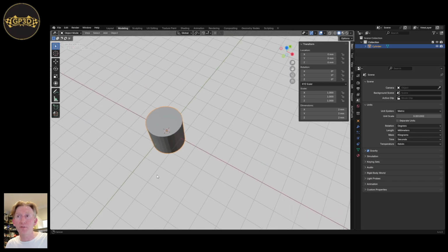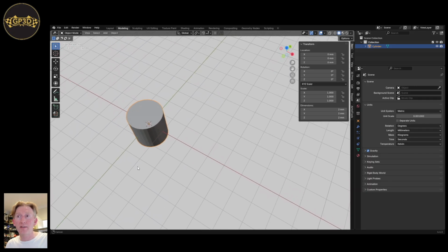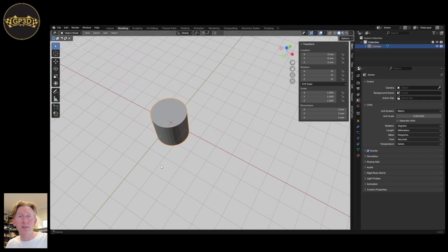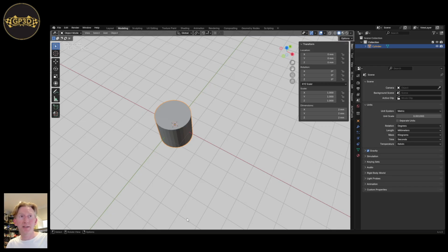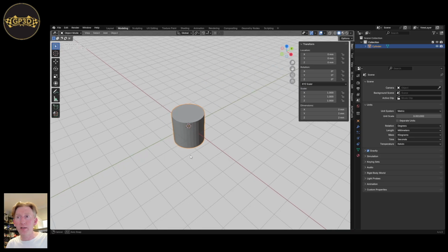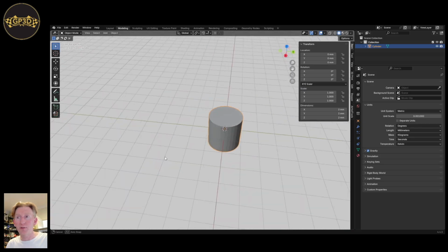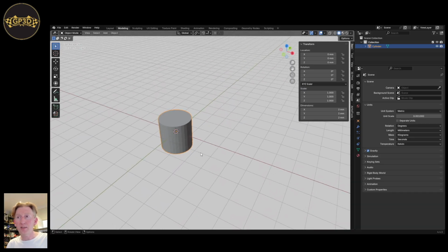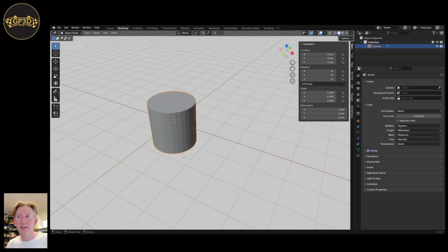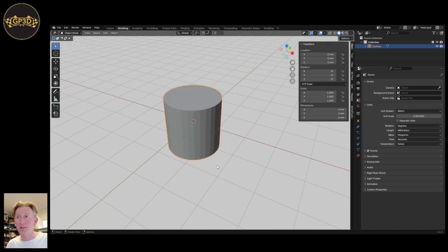So you can move the object around the view to get it where you desire it. Okay, let go now. And then back, hold down the mouse scroll wheel, I can move around the object itself. Let go of that. If I just scroll the scroll wheel in and out, I can zoom. So just a quick navigation recap.